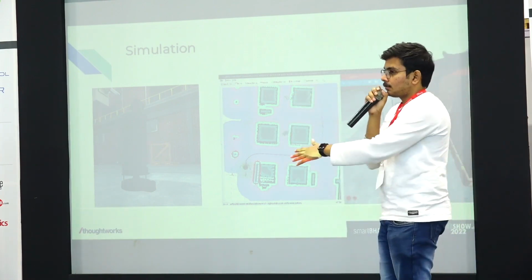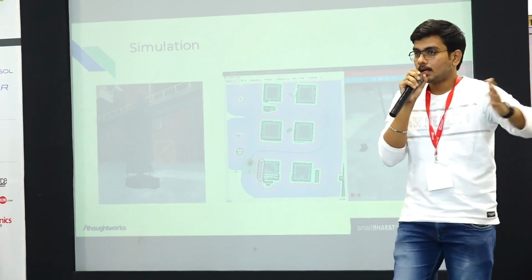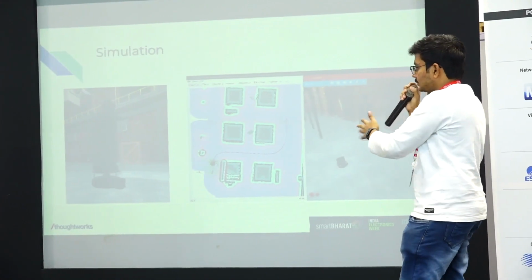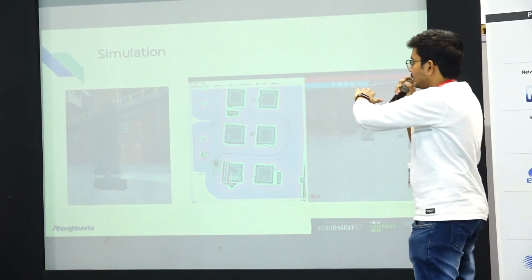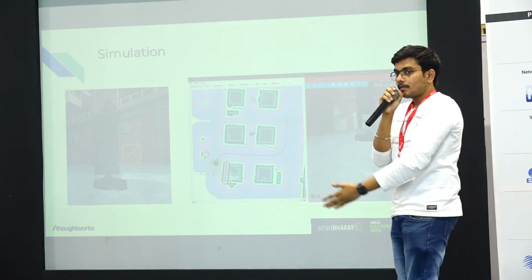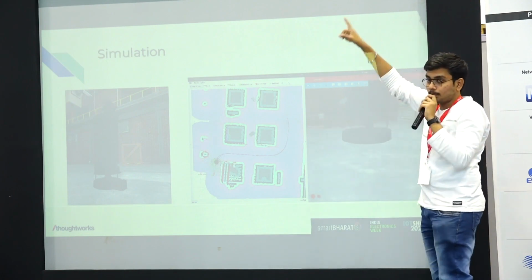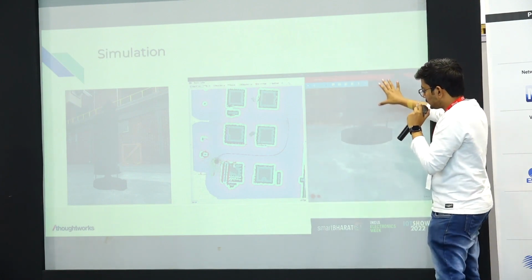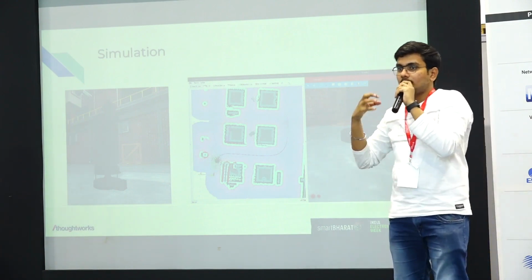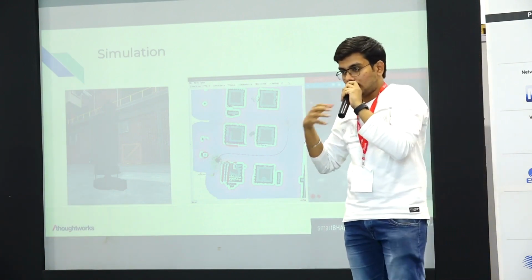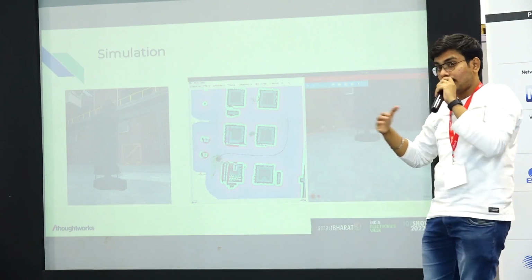We are from the autonomous vehicles domain. There are multiple AV simulators in the market, but for the indoor robot, which is 1/10 of the autonomous vehicles running outside, we have a simulator called Gazebo. It's open source, and we have actually used it. If you see here, this is the real bot that I showed you before, which we have done in the simulator environment. A simulator is nothing but a physics engine. So we need to specify the inertia and mass of our design, so that it will give how it will react in the real world, or something near the real world.